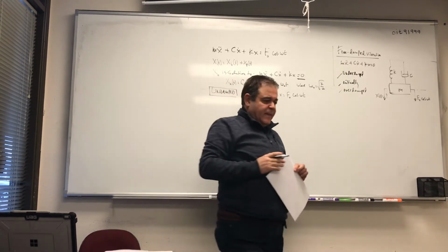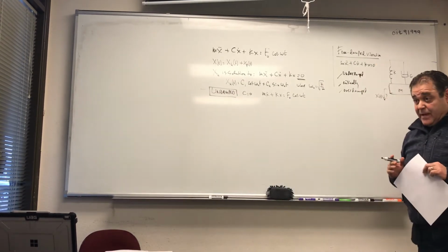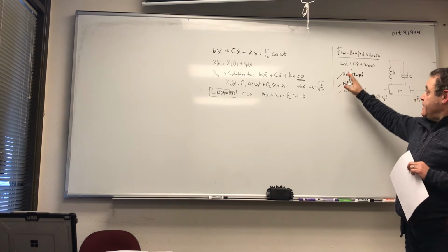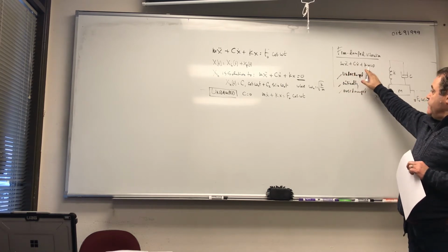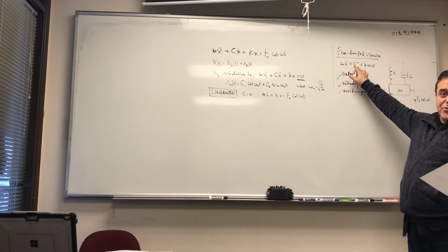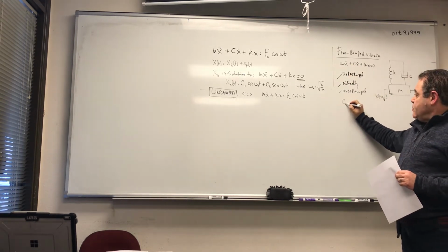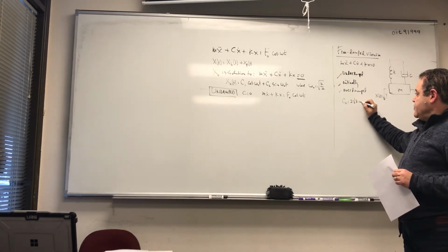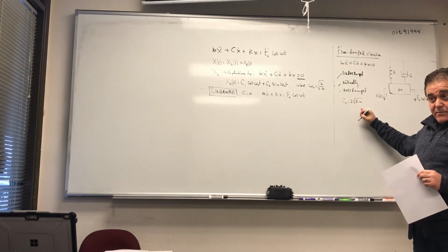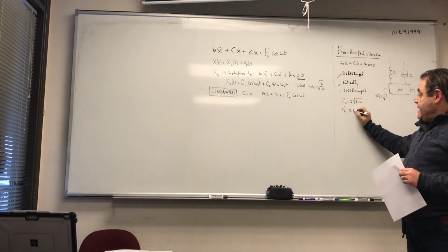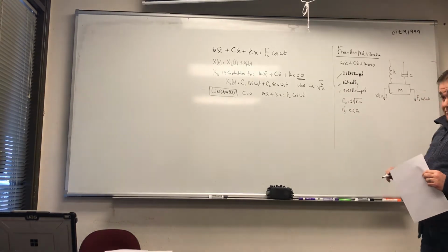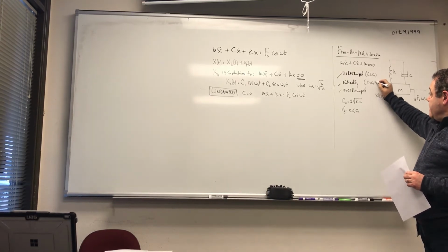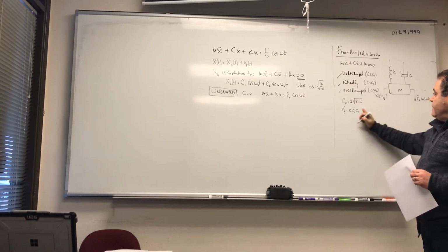The ratio of C to CC. I gave you an example last week. If you are given a problem like this, the first thing you can figure out is C, because you just read it directly off the equation, and then CC is equal to what? 2 root km, exactly. So you know the spring stiffness, you can find CC. Now if C is less than CC, that's the under damped case, C equal to CC, and C greater than CC.